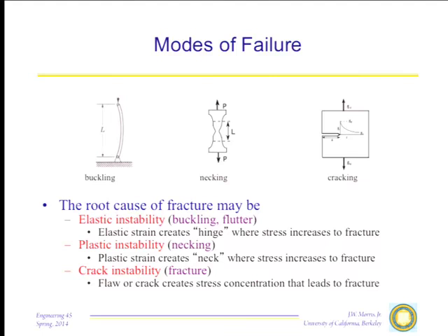That's an elastic instability. A similar elastic instability, and a much more spectacular one, is flutter, where you have something like, unfortunately, the wing of an airplane. It's happened before. I've investigated it before, where you begin to see it bouncing up and down. If you're flying around, look out the window. The wing of the airplane is doing this. Well, now let's suppose that in doing this, you happen to hit a natural frequency of the wing.